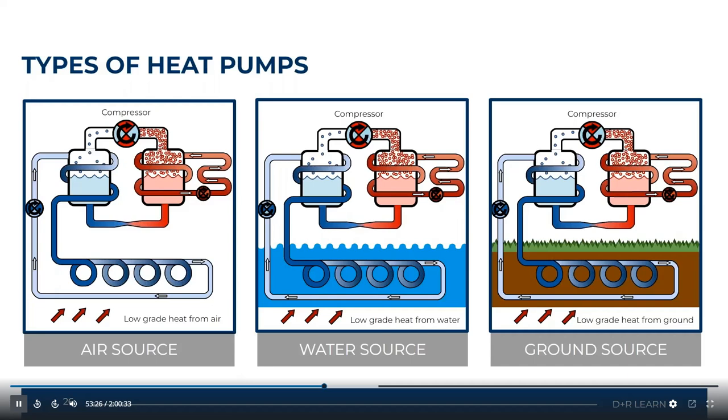And that's because that year in San Antonio, the temperature dropped below 32 degrees. Now, around that time, heat pumps were not able to operate without auxiliary or backup heat, anything under 32 degrees Fahrenheit. But in the last few years, we have been able to work on the refrigerants that will allow us to take the operation of those systems even further down as far as ambient temperatures are concerned.